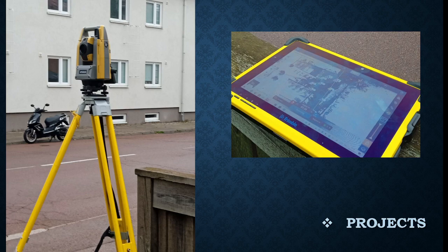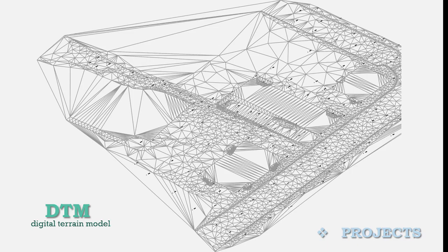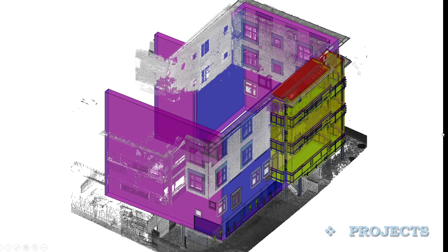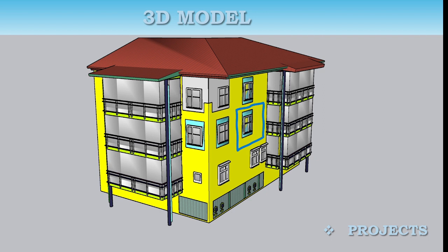To complete the project, a Trimble laser scanner was used to survey and create a 3D model of the territory and landscape. As a result, a digital terrain model was created and the marks were obtained, based on which engineers make decisions about how the reconstruction will proceed. Here is a fragment of digitalization of the facade of the building that will be adjacent to the new office. The place where the transition from the new building to the existing building will be implemented is marked with a blue rectangle.